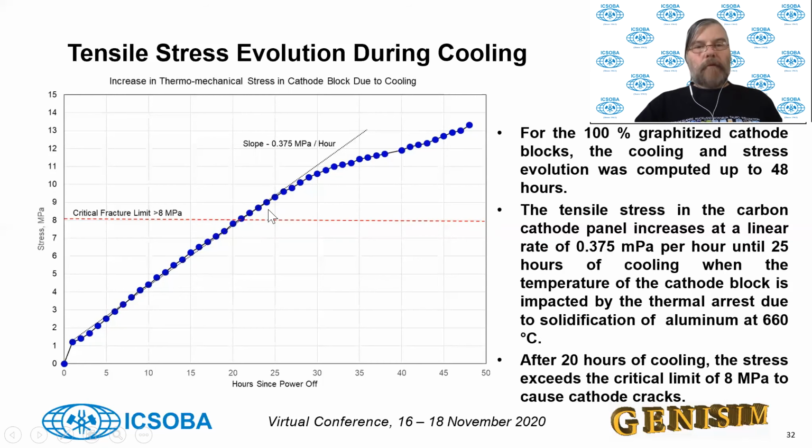But what's important is the prediction that at about 20 hours, we are reaching the limit where the cathode will start to crack. So if you pass the limit when you cannot restart, you will have to endure the full damage of your cathode.